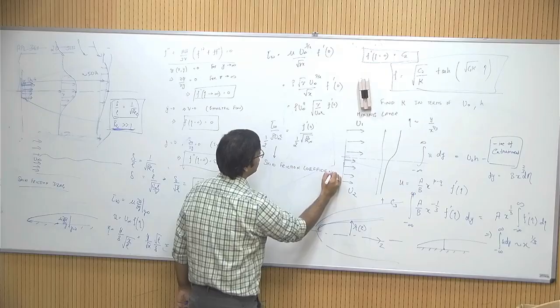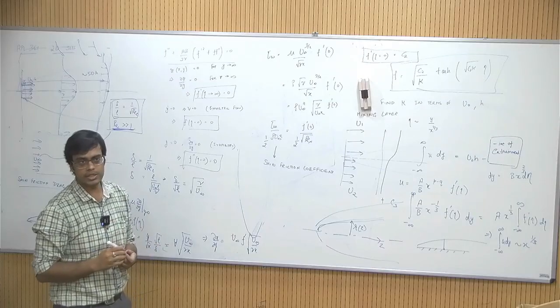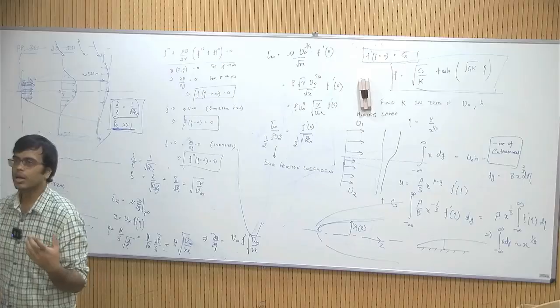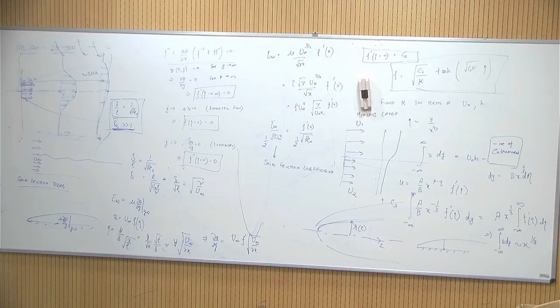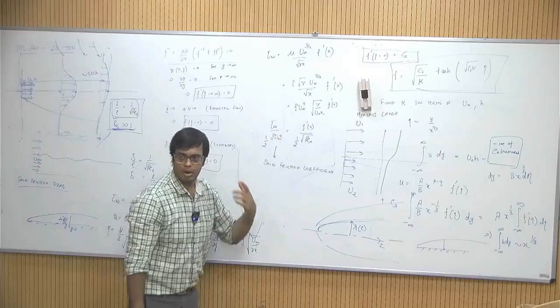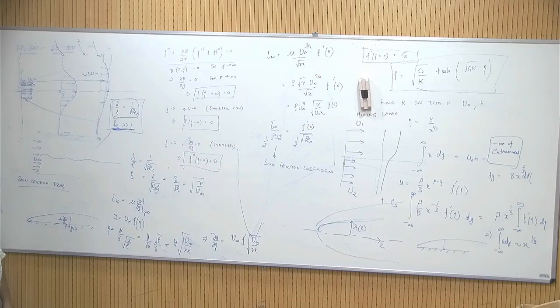Okay. On top also you have units of stress, and bottom also you have units of stress. It's a dimensionless quantity. It's very similar to your drag coefficient or whatever coefficient you want to formulate. Force over rho u infinity square times area. There is no area, we are working with stresses, so it is force per unit area divided by some dynamic component of stress that you can formulate to non-dimensionalize.